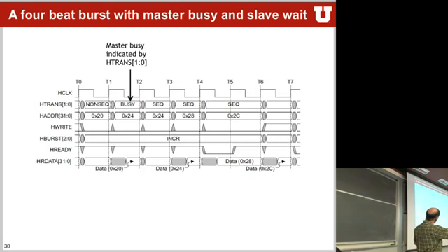So it's busy, 24. It waits with the data for 24 until the next sequence step, sequence data over here, because there was a wait state. In this particular case, the burst is an incremental burst, and you can see that the address always increments by 4 unless you have a busy state up there.